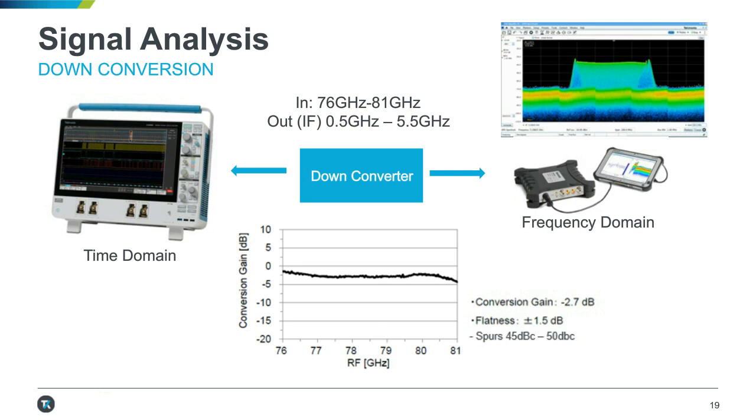You're moving from 3 gigs to 7 gigs, and so if you've got a very large harmonic in that system, when you're at 3 gigs, you're going to get a harmonic at 6 gigs. So these are some things to take into consideration when you're trying to do a measurement of this type.